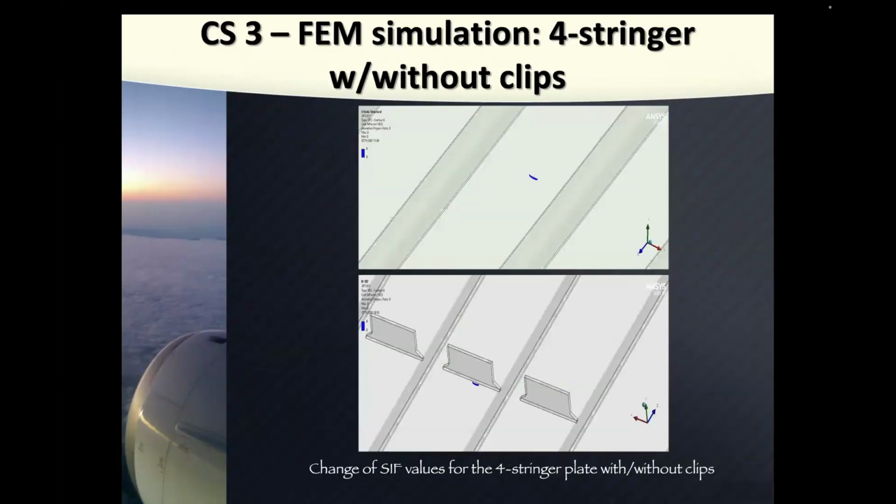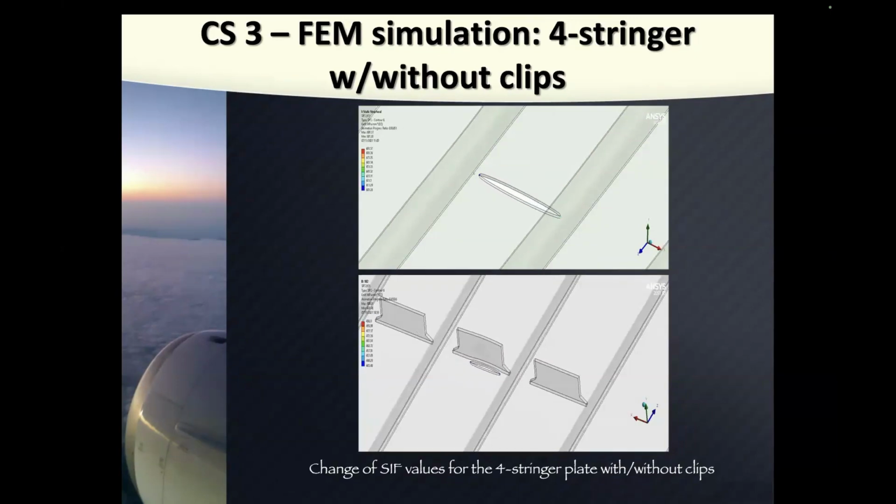Yeah, so these are images from ANSYS simulations. And they also used here so-called clips, because they wanted to check, can we somehow stop or slow down these cracks using additional elements? So these elements are called clips, okay? And then you can see the crack is now growing along these clips.